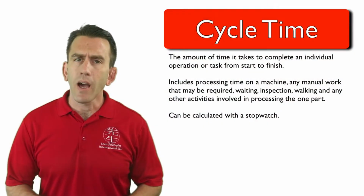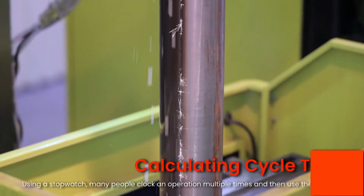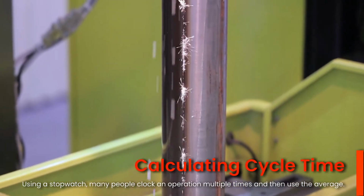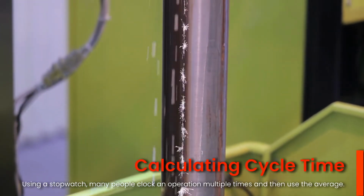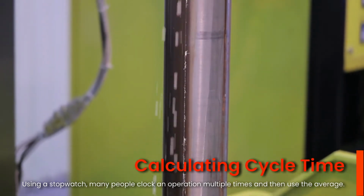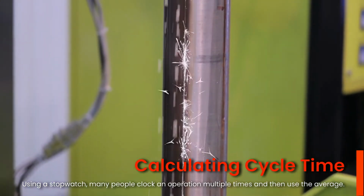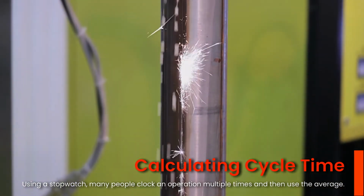Cycle time can be calculated with a stopwatch. In addition to calculating your cycle time with a stopwatch, one of the most common ways to calculate a cycle time is to clock the operations multiple times, for example, 3 to 5 times, and then use the average cycle time as your standard cycle time.